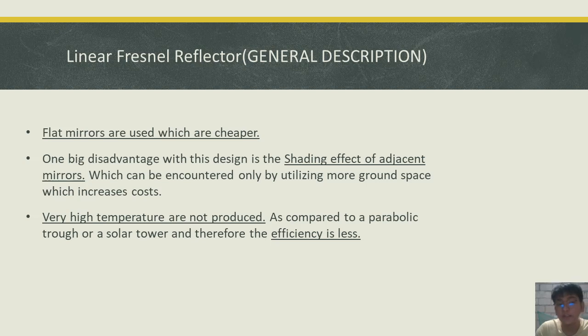Okay, these are the advantages and disadvantages. The advantage of LFR is that it uses flat mirrors, which are much cheaper than the curved mirrors used in parabolic troughs. One of the big disadvantages of this design is the shading of adjacent mirrors, which can be avoided only by using more ground space, which increases the cost. Very high temperatures are also not produced, as compared to the parabolic trough or the solar tower. Therefore, their efficiency is less.